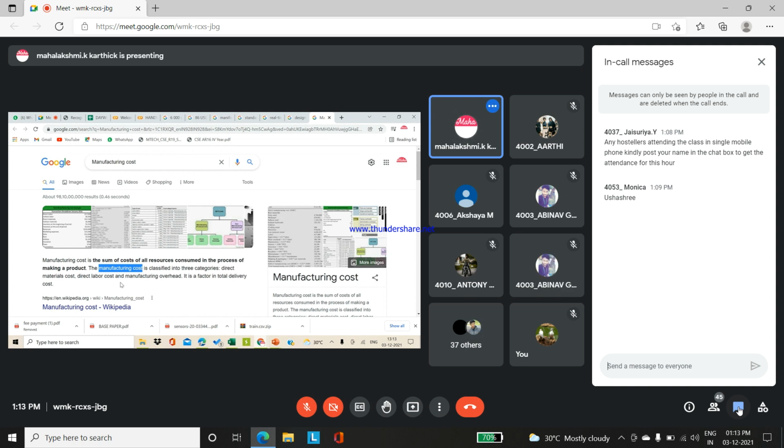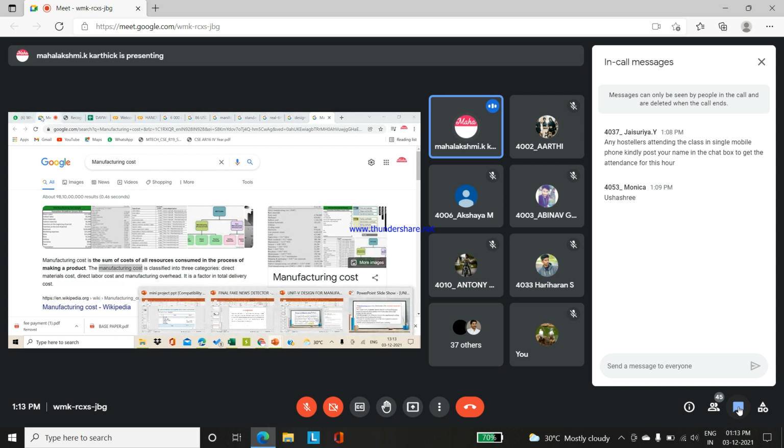Specifications are mentioned by the customer, whether dimensional specifications can be fulfilled, and whether molding machines or the type of equipment are available or not. That's why, starting from the development stage, planning stage, concept selection stage, architecture stage, or industrial design stage, the manufacturing design team will have proper communication with all the activities involved in the product development life cycle. You have to keep this in mind.